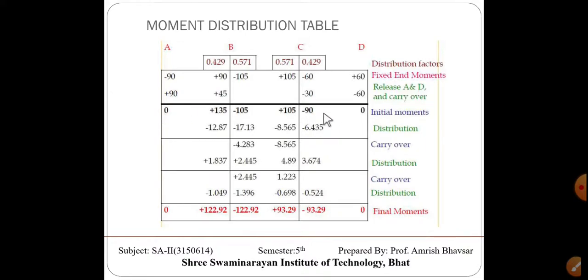So now finally what will we get? We will get the initial moment for the distribution of the moment. So here it is 0, the summation of these two is 135, this is minus 105, this is plus 105, this is 90 and this is 0. Now we have to take the distribution, and how will we take this distribution? We have to multiply this support moment with the distribution factor. Here 0 is multiplied with 1, so it is 0. At a simple support all the moment must be 0, so we can directly take the final moment as 0. But here we have to sum these two and multiply with this distribution factor, and we will get the value minus 12.87. Again we sum these two and multiply with this, and we will get 17.13.